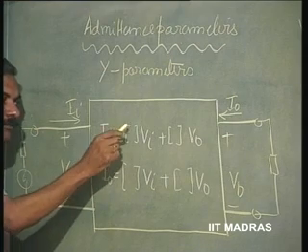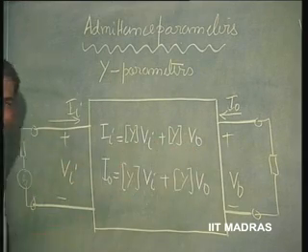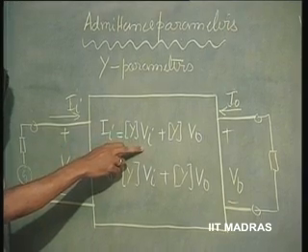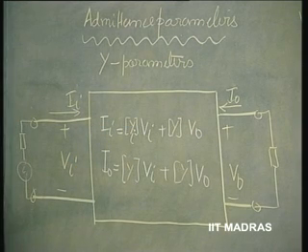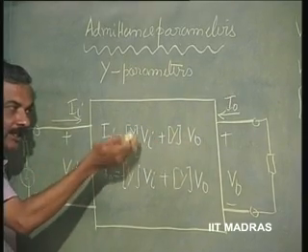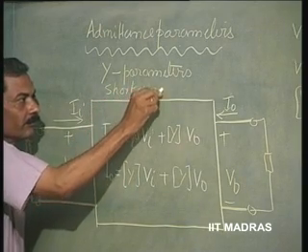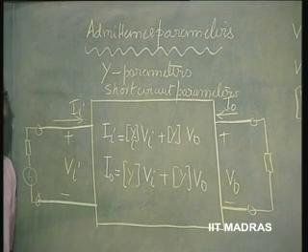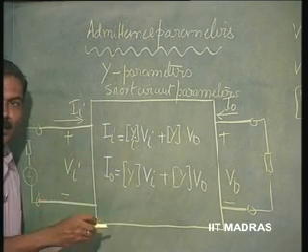So, that means II is some Y into Vi, again Y some other to V0. These Y's have to be respectively defined now. All these are admittance parameters. Dimensionally they are admittances. So, II related to Vi, again it is input, totally. That means Yi. And how does that get measured? When V0 is 0. So, either Vi should be 0 or V0 should be 0 in order to measure all these parameters. That means these are called short circuit parameters as against the earlier parameters which were called open circuit parameters. So, I make V0 0, then I can measure Yi as II by Vi.